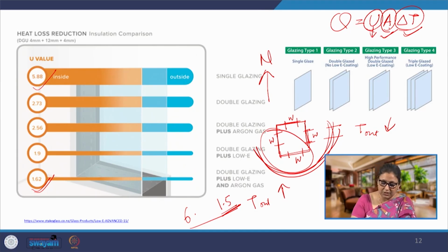So, what happens if I reduce my U value to 1/4? Originally I had 6 and then I take 1.5, which is 1/4. Directly my heat exchange is going to reduce by the same proportion. The U value is 6, and the rest remains constant, A into delta T. So, Q1 is equal to 6 times C, and Q2 is equal to C into 1.5.